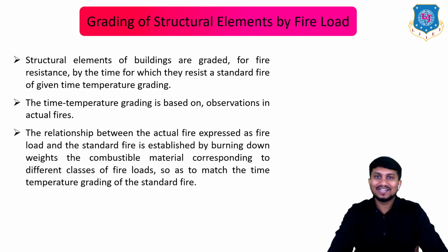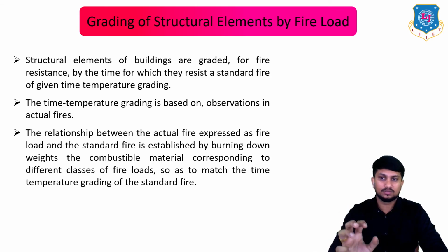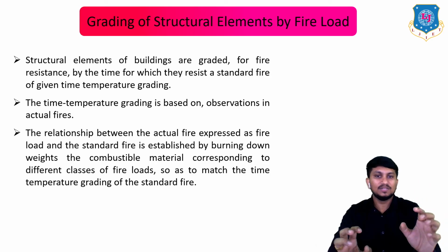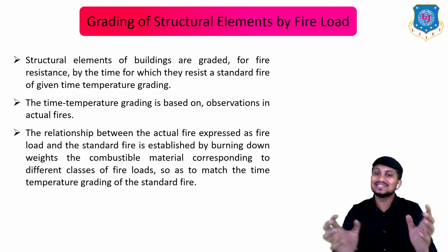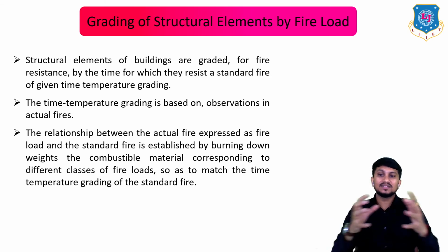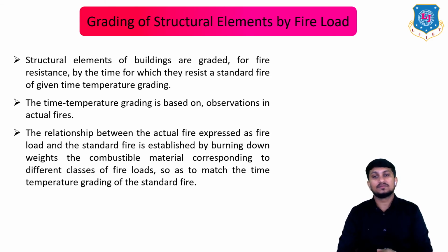Okay, now let's see the grading of structural elements by fire load. The structural elements of a building are graded for fire resistance by the time for which they resist the standard fire of given time temperature grading. Okay? The time temperature grading is based on observation in actual fires. The relationship between the actual fire expressed as fire load and the standard fire is established by burning down weights of combustible material corresponding to different classes of fire loads so as to match the time temperature grading of the standard fire.